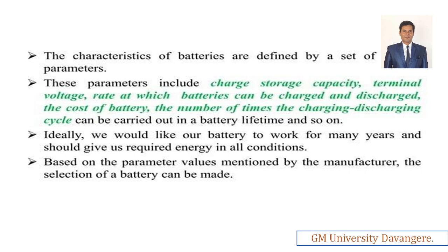Right. So parameters include the charge storage, right? How much energy it is going to store, its capacity, and what the terminal voltage is when there is no load connected, with respect to the internal resistance of the batteries, and also the rate at which the batteries can be charged and discharged. The cost, how cost effective the batteries would be, and the number of times of charging and discharging, the life cycle. The life cycle depends upon how much it will charge and how much it will discharge.